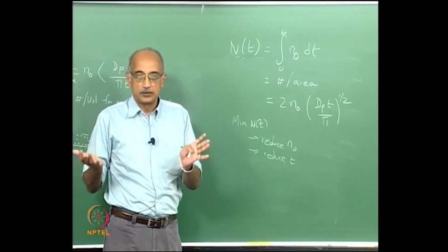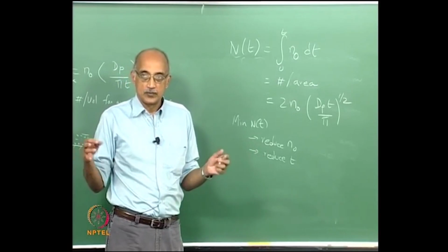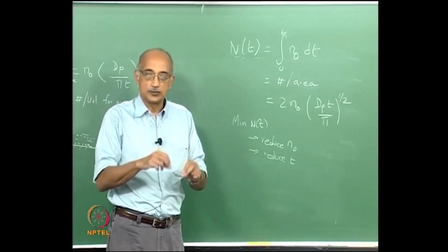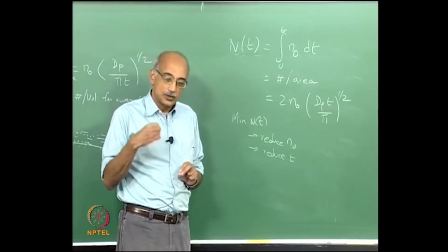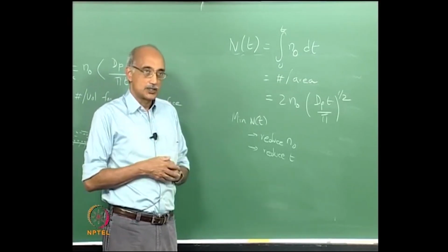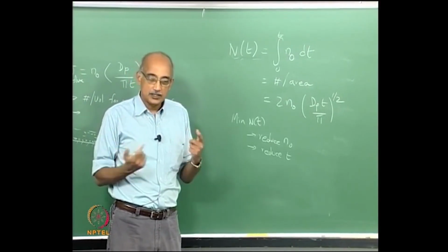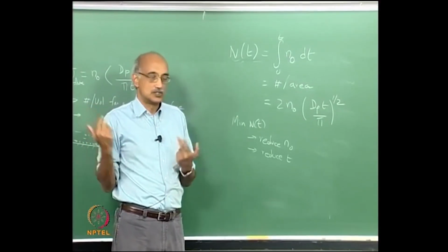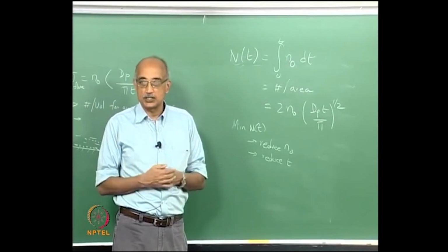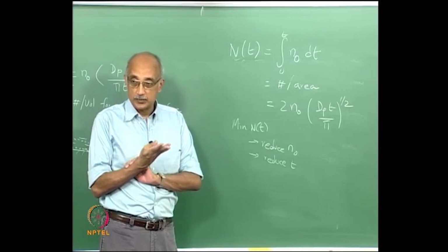So you don't have components just sitting around in a room for a long period of time waiting for somebody to use them to build a product. It's also known as just-in-time manufacturing. The components are delivered to the process just in time, just when you are ready to use them. So this combination of CFM, just-in-time, WIP minimization, all these strategies are good from a manufacturability viewpoint.